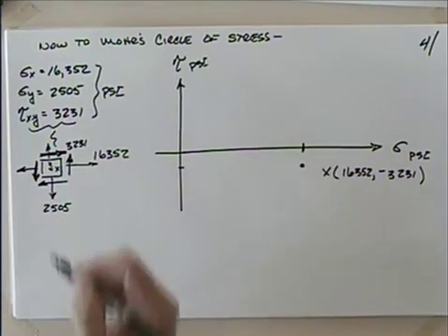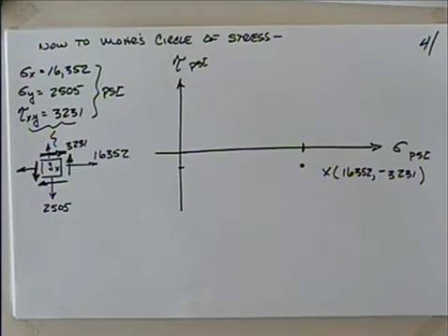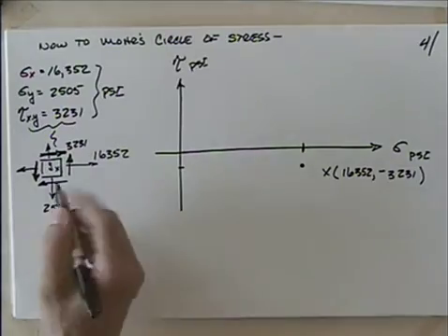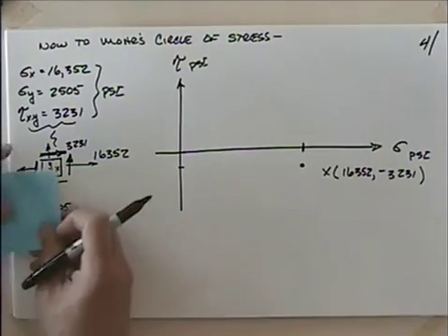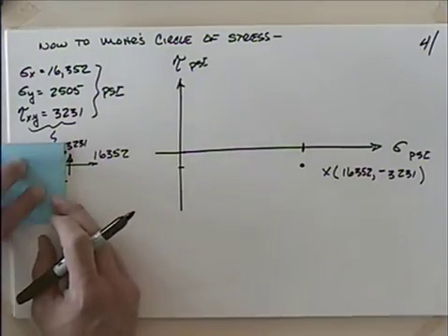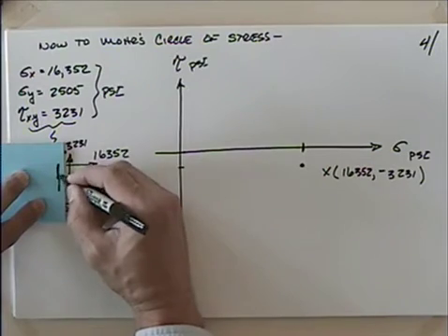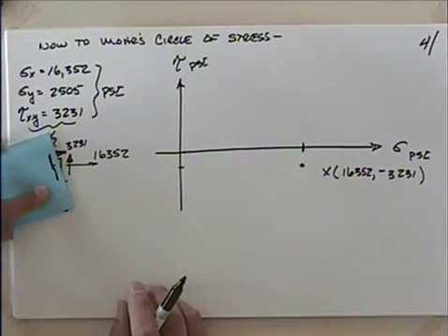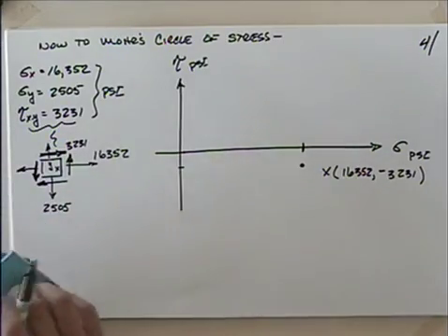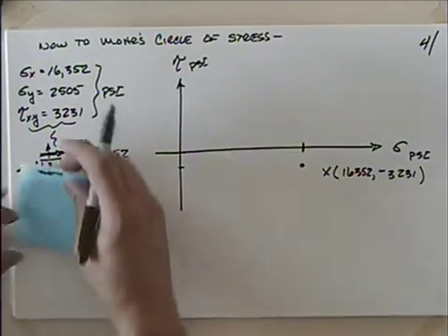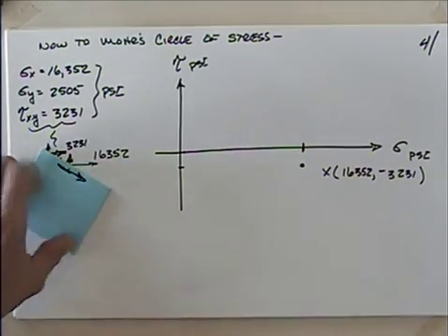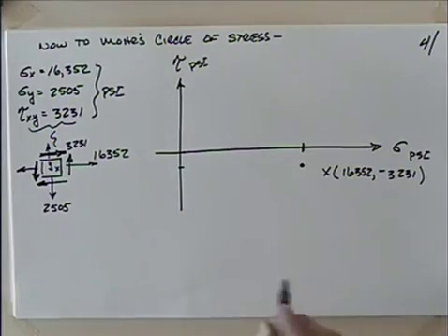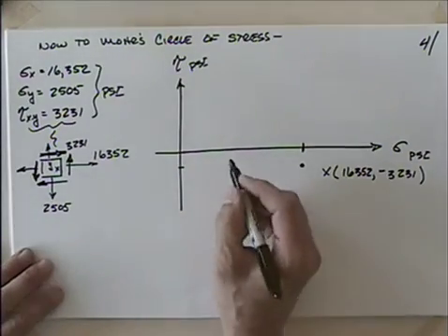And I'm kind of recapping this because this will be our last problem with Mohr's circle of stress or Mohr's circle of strain. So now when you look at this element, you think about which way does the x tend to rotate. If we ignore these others and we just look at that, that would tend to rotate this counterclockwise. So I plot that negative, right? And then what if we have this one up here, the y? What's the y going to do? It's going to rotate it clockwise. So we'd expect x to be plotted negative, it is, and y should be positive, which it is.